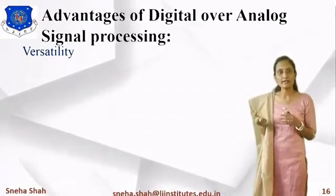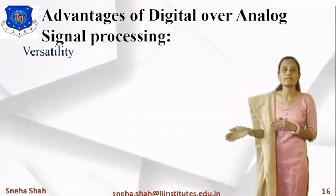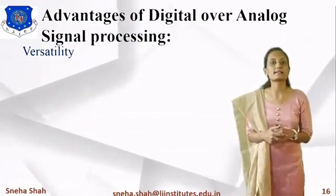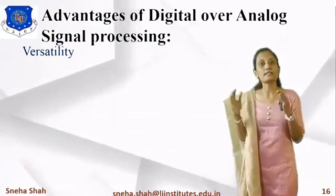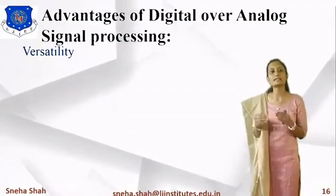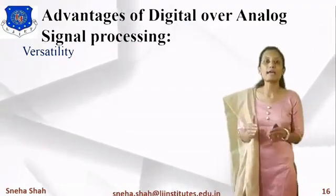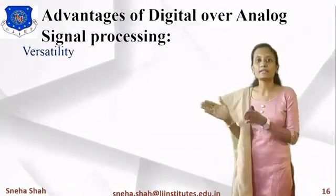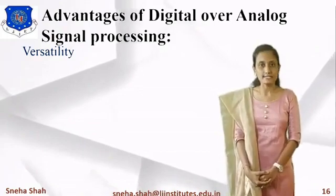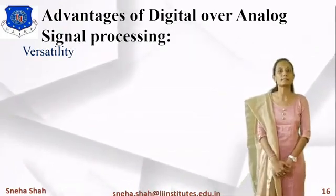By using only one chip, we can use different hardware, and because of that, we can design different applications. That we consider as versatile. So it is more versatile compared to analog signal processing, because in analog signal processing, for different applications, we have to design different hardware. But this does not happen in the digital signal processor. So this one is the advantage of digital signal processing.